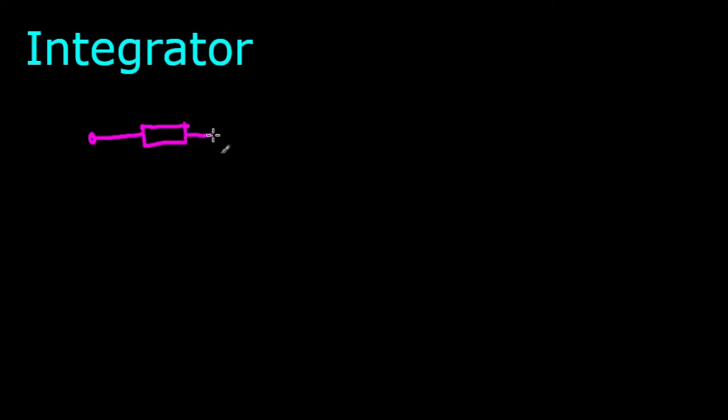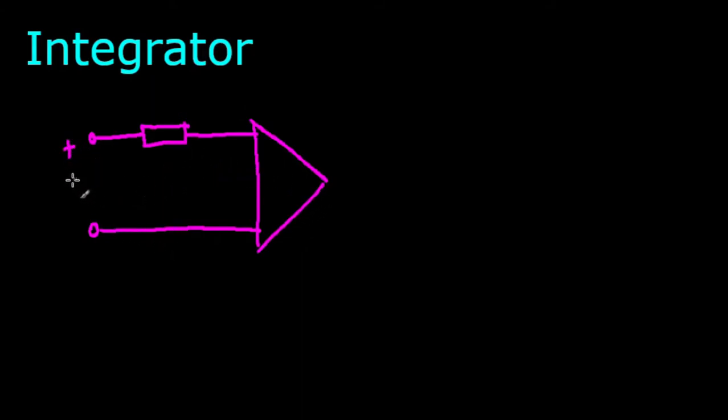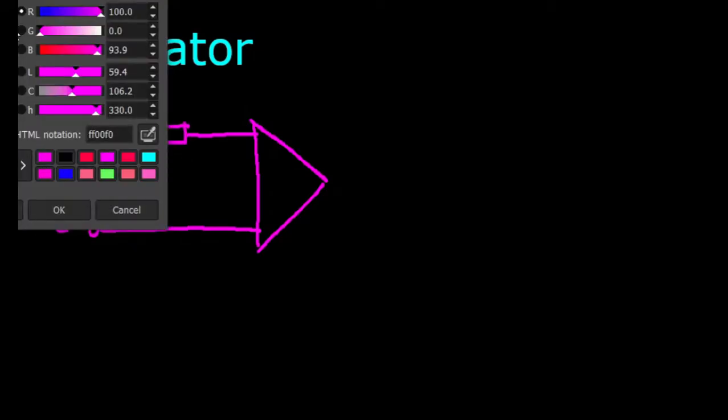Another thing about this circuit is that I'll draw it in a way that you'll see in most op-amp problems which don't involve summing op-amps. It's drawn something like this. They don't draw your ground explicitly. They don't mark this as the ground. Instead of saying V1 is this potential, it's the voltage between these two terminals. It's really the same thing as we did before. There's really no difference in functionality, just a different way of drawing this.